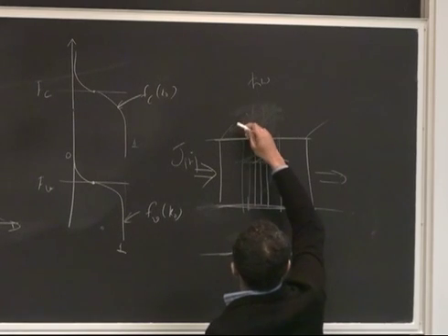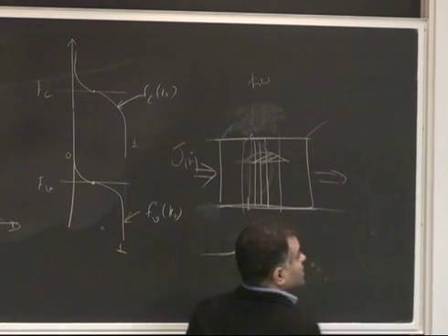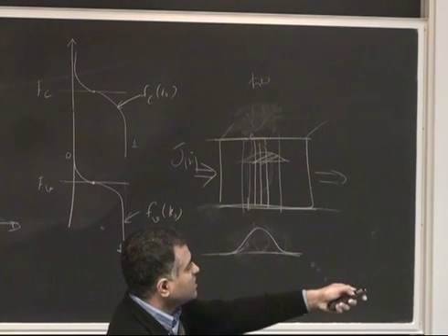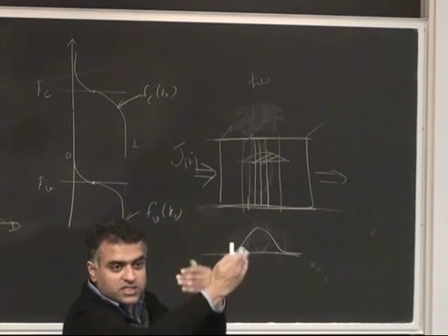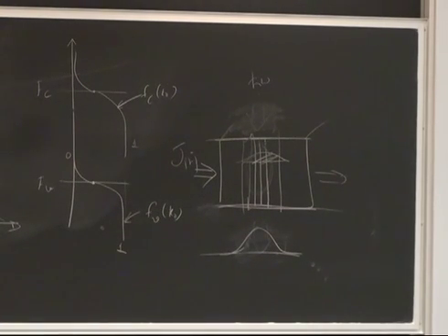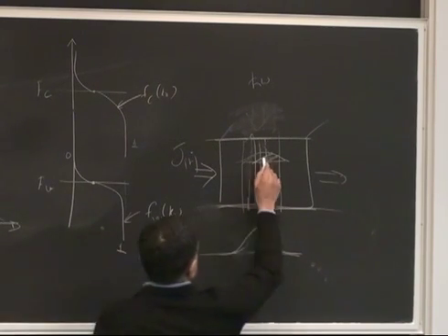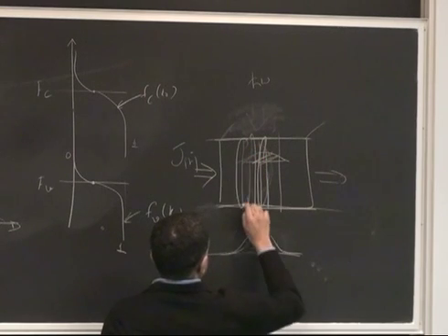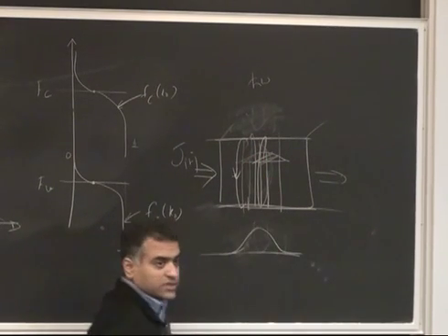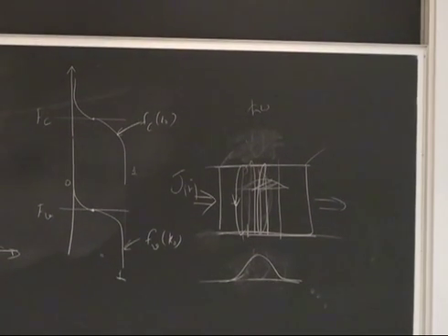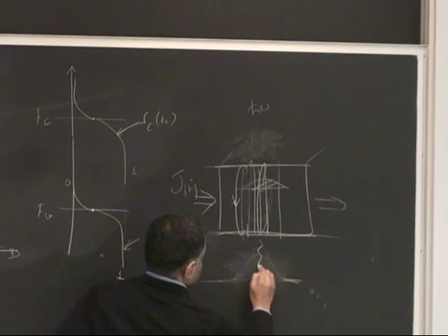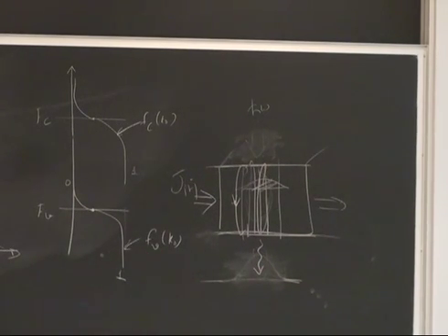So essentially what I'm trying to say is this is a p-n junction now injecting carriers, and then this face and the other face on the other side. These are the two mirrors. You just cleaved it. This is the cheapest way of doing it, and then essentially those are the two mirrors, and the light, this mode, kind of bounces back and forth in between these two, and that's your gain medium now. So the cleaved facets, this is called an edge emitting laser because the light is going to come out from the edge of the wafer. So it's the edge emitting laser, and then it is going to come out along the sides,